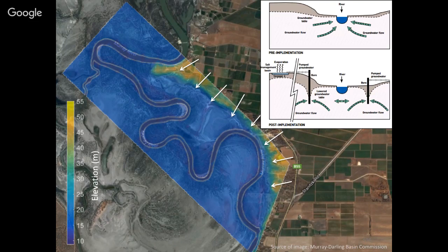Suppose you could take some wells out here and pump the saline water out, put it into evaporation ponds up here, to reduce the hydraulic head here and perhaps get saline water to move up this way and increase the amount of fresh water that is there.